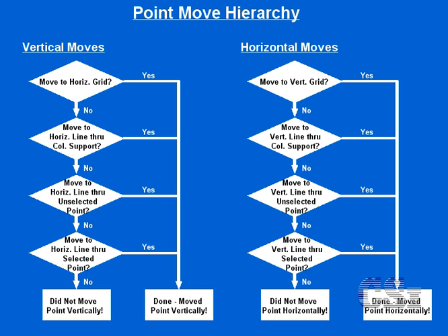Please note that once a point is moved in a specific direction, it will not be moved again in the same direction for any of the conditions that may follow. It is important to also note that when checking against lines through points, it checks the points in the order drawn. From this flowchart you can see that this command has many conditions to check, which in turn are very order dependent, and thus it is important that you understand this option before using it in any substantial manner. Now let's see how this works in reality.